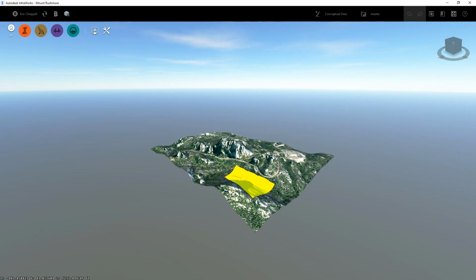Anyway, so unfortunately, the old permissions and setup in the old collaboration environment in InfraWorks is not going to carry over. So whatever your team was that you had constructed and the people as well as their permissions, that's all entirely different in BIM 360. So you're going to have to reestablish that in BIM 360. Like right now, my Mount Everest project, I just created it. I haven't added anybody. If you're creating the BIM 360 project for the first time, you're going to be in the same spot, and there's no file that you can export from BIM 360 or anything that can migrate it over. Luckily, as you're going to see, it's really easy to add users and set permissions in BIM 360. So I hope you'll agree it's not going to be super hard to take care of that.